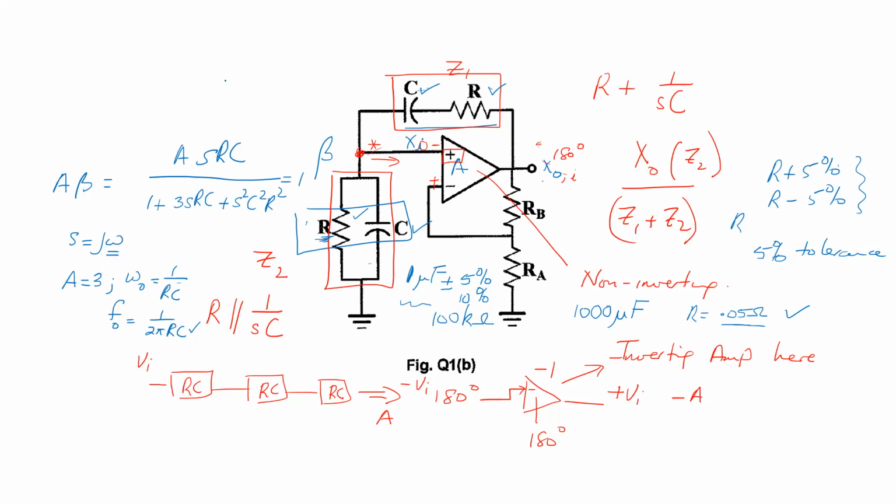If the circuit is asking for 55 kilohertz, as I think the question does, then 55 kilohertz means that either the resistor or the capacitor is going to be small. So you have to pick one of them. You pick a smallish capacitor and then see what value resistor you come up with. If you pick a big capacitor, to make this work, the resistor is going to be incredibly small, which is the little joke I was making. But you have to pick one or the other.